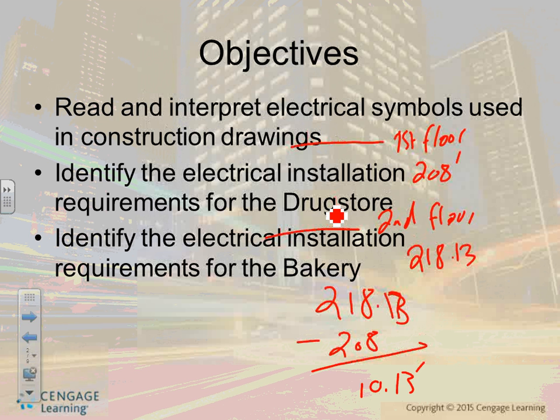You can do this in Revit easily, guys. You can put a section view in Revit anywhere you want, and you're going to be using this called section view. You drop a section view. I want to see the hallway. You drop a section view from that corner all the way to here. The minute that you finish it, it will draw a section view of the hallway. So easy in Revit, so easy. Any view you can section view. It's called section view.